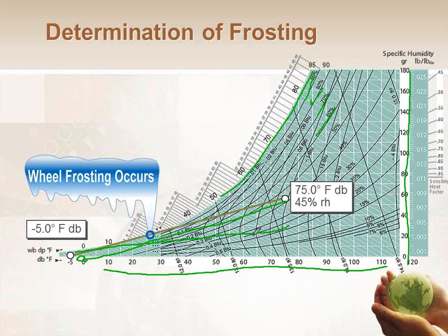However, that outside air I heated coming in, if I have a 70% effective wheel, 70% of that's going to get transferred over to the exhaust air and thrown away. So I probably don't want to heat the outside air coming in. I probably want to heat the return air leaving the building, which sounds really weird, but that return air, if I heat it, it's actually going to go into the wheel, and I'm going to recover 70% of it there and save that energy. So if I actually heat that air, from, say, 75 to 85 or something like that, then redraw my line.